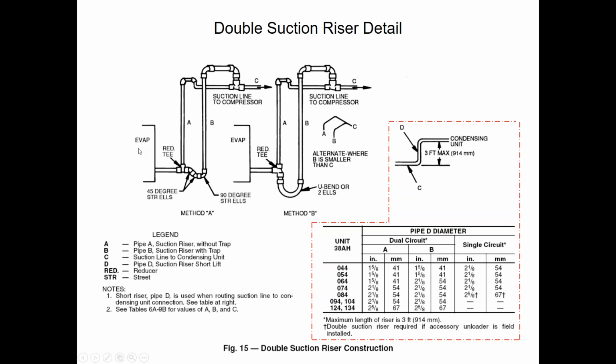All of our evaporators are DX evaporators. For our split systems, we use 1/2-inch tube in the evaporators. If you're trying to retrofit a 410 unit on an older evaporator, look at the tubes and make sure they're not 5/8. If they're 5/8-inch tubes in the evaporator, guess what? You've got to change it. You can't use a 5/8 tube evaporator on the new 410 units.